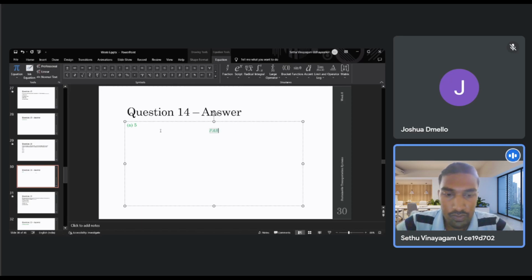We want to find out the floor area ratio, FAR. As we saw earlier, this is nothing but the total floor area divided by the size of the plot. What is the size of the plot? It is 1,000 square feet. And what is the total floor area?